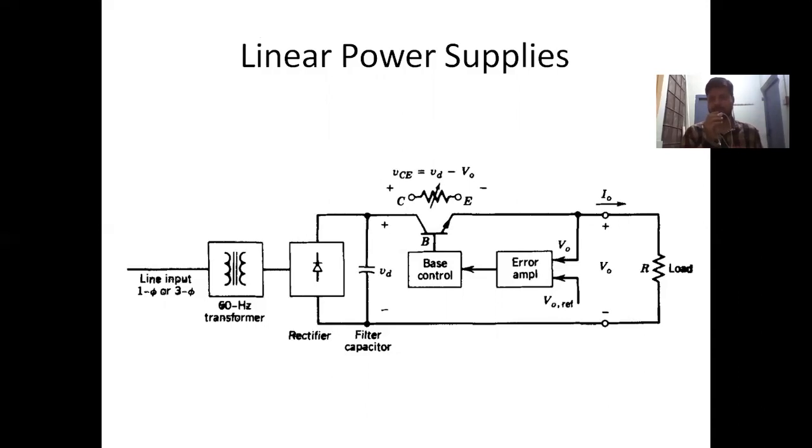rectifier output. And after that capacitor, you had a 7805 regulator IC. And that regulator IC maintains plus 5 volt even if the input changes within a finite or specified range, or even if the output changes.